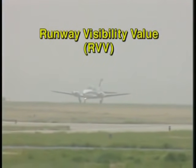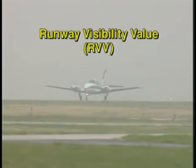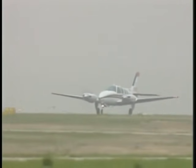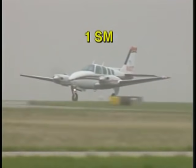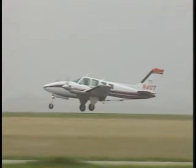Runway visibility value, or RVV, is the distance down the runway that you can see unlighted objects or lights of moderate intensity. This value is generally derived from an electronic measuring device and is listed in miles or fractions of miles. When available, RVV is used instead of prevailing or tower visibility.